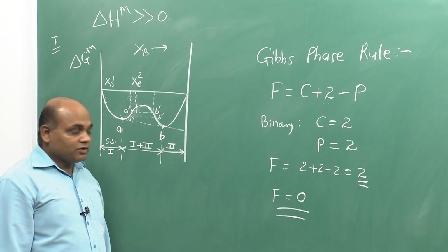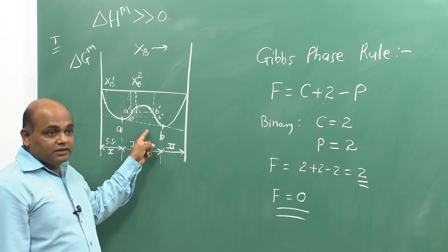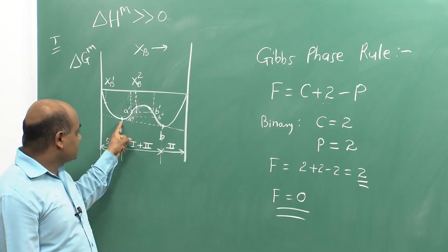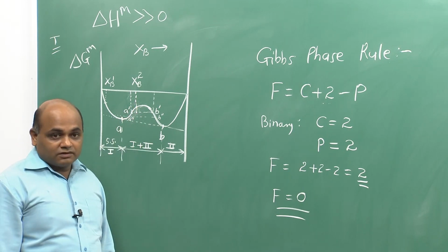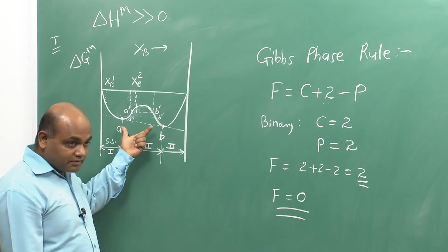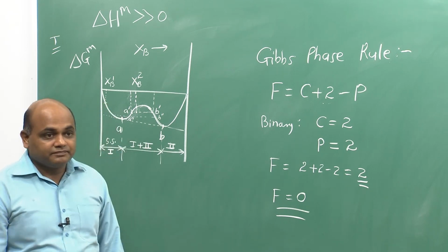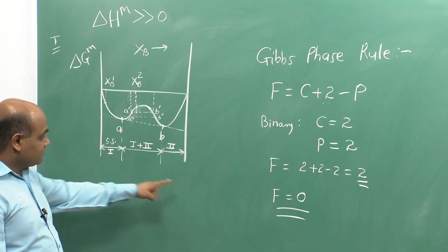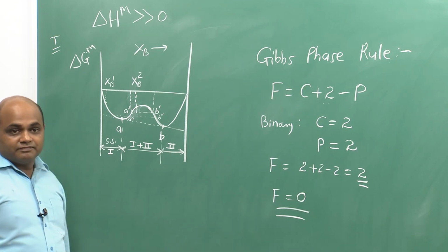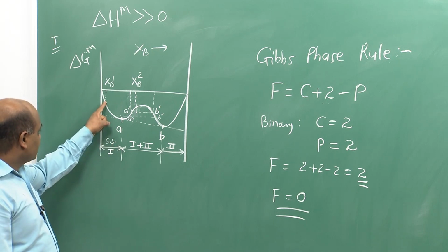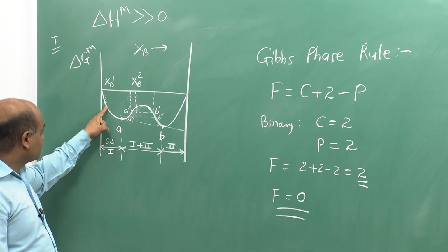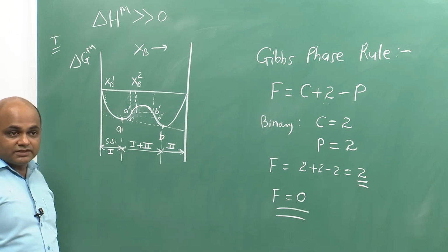Okay. So, we cannot vary the composition. Once we fix the overall composition, that is it, the compositions of the 2 phases in equilibrium are fixed. Whereas, in the single phase region we will have 1 degree of freedom, right. So, if you see, there is a degree of freedom of composition, you can vary the composition and still be in the single phase region.